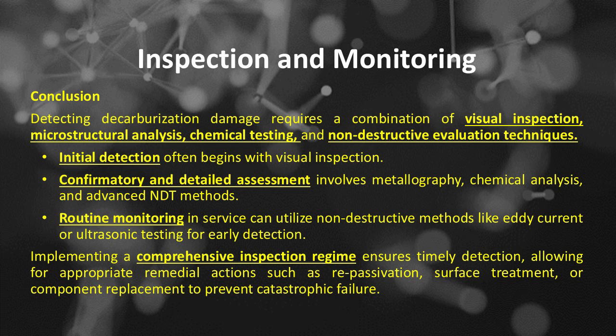and non-destructive evaluation techniques. Initial detection often begins with visual inspection. Confirmatory and detailed assessment involves metallography, chemical analysis, and advanced NDT methods. Routine monitoring in service can utilize non-destructive methods like eddy current or ultrasonic testing for early detection.